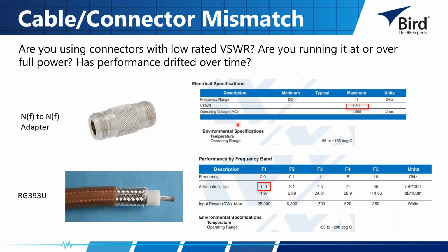And again, a good thing to always keep in mind when we're looking at cables and connectors, because we're talking about that relationship between the center conductor, dielectric medium in between, and an outer conductor. Things like temperature are going to play into making certain materials more lossy. Resistivity is going to increase over temperature. We're going to have some different effects coming into play there that can affect our measurement, especially on a cable.